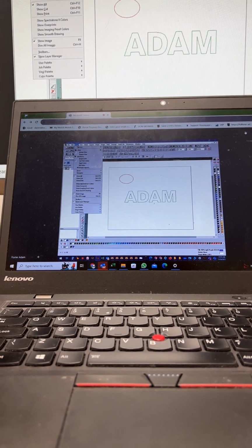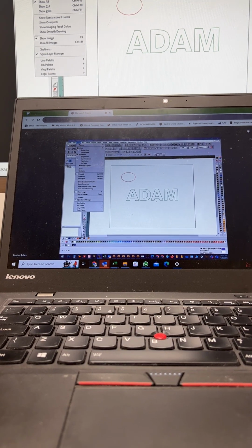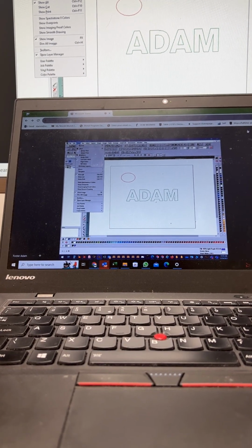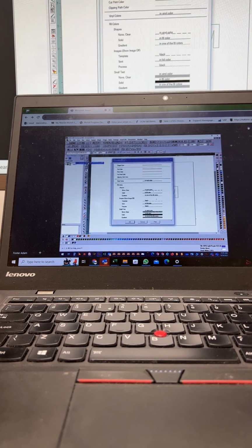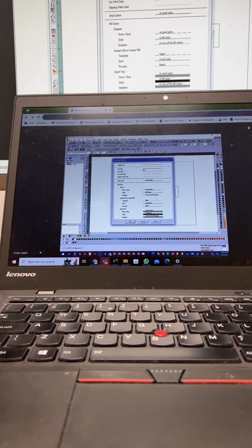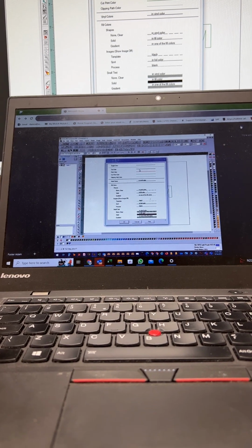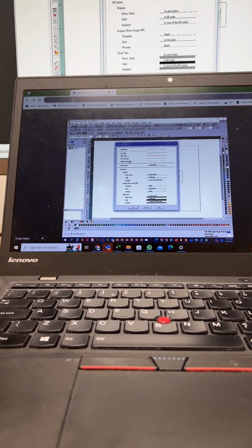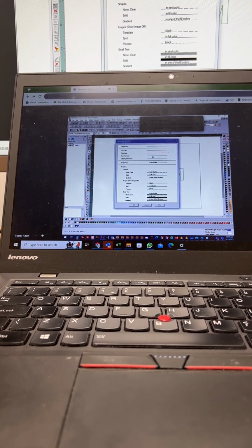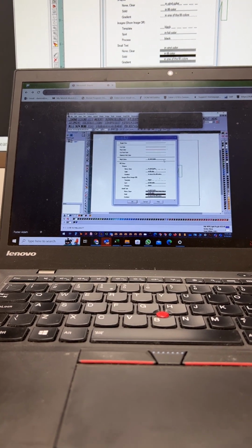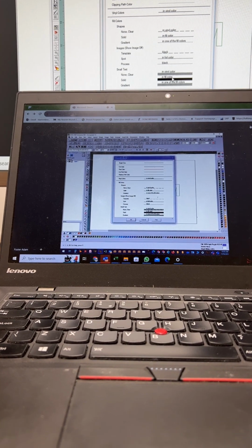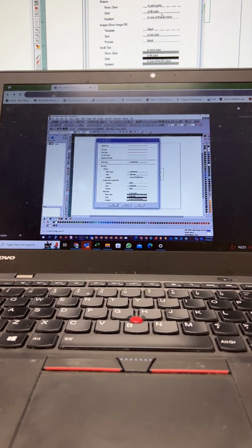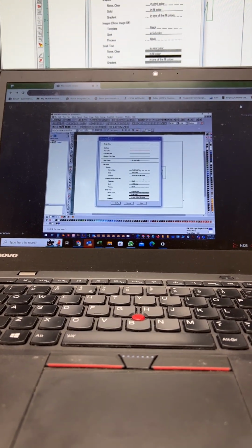Let's see. If you ever wonder or forget what all this stuff is, because it'll probably be a couple weeks before you see the software again, at least, you can go to Wireframe Legend, and it'll tell you what all the actual colors are. So cut color is black, print color is red, print color is green, and then vinyl colors and all the other different dashed lines when you're doing different stuff. But that gets into more advanced things. Shouldn't have to worry about those.